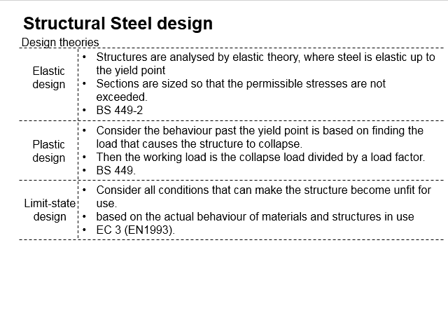In structural steel design, there are three typical design theories, which include the elastic design, plastic design, and also limit state design. For the elastic design, structures are analyzed by elastic theory, where steel is elastic up to its yield point. The sections are sized so that the permissible stress within the members is not exceeded. Such design is in accordance with BS 449.